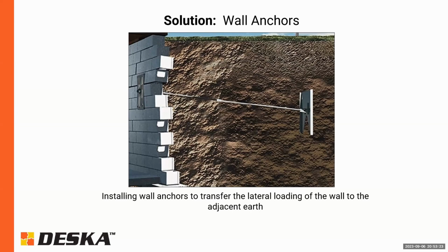We generally prefer to use the straps or the struts. We prefer not to anchor the wall with the soil outside, especially since the soil expands and contracts. So we prefer to anchor to something that we know is not going to move as opposed to something like soil. The one upside to a solution like this is if you tighten it on a seasonal basis when the ground is drier, you can potentially straighten the wall, but I wouldn't count on it, but it is a possibility. We typically would use these only when there's certain circumstances that this is really the only option.